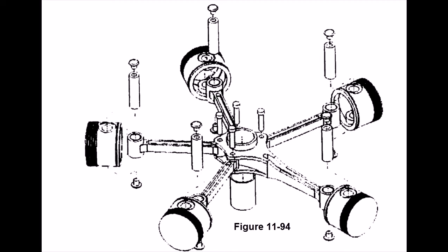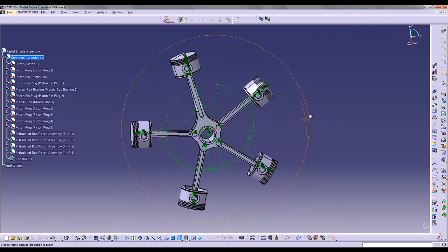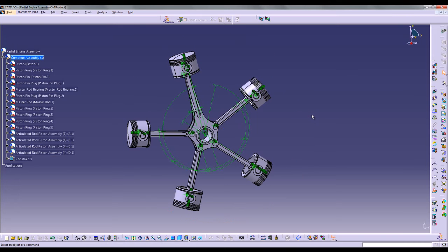And also, for this tutorial, we recommend that you constrain most of the parts, not all, but most of the parts to the origin, just to simplify the process of creating an assembly. Normally this would not be the case, but for this assembly it'll be recommended.